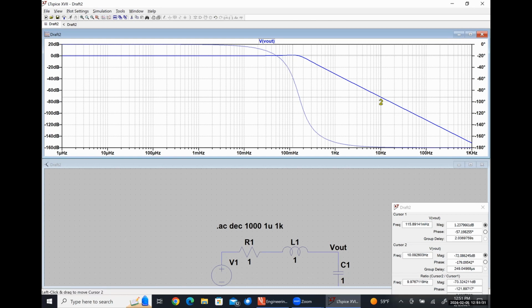So while it does look roughly the same, we are actually rolling off at that 40 decibels per decade instead of 20 decibels per decade. So we see that we transition from the pass band into the stop band much more quickly once we go beyond that little uptick in the system's response. Okay. So it's a better low pass filter in as much as signals beyond its frequency, the cutoff frequency, get cut off more quickly. However, we accidentally see a little bit of amplification around the cutoff frequency, which might not be great.